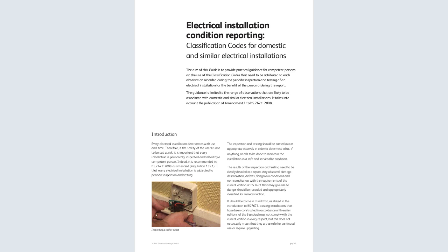Somebody remind me. They are the four main tests. That is the earth loop impedance, the insulation test, the polarity test. Somebody give me the last one. Somebody who remembers the last test that we talked about? Continuity of protective conductor. Good. That is there. Those are the four main tests.